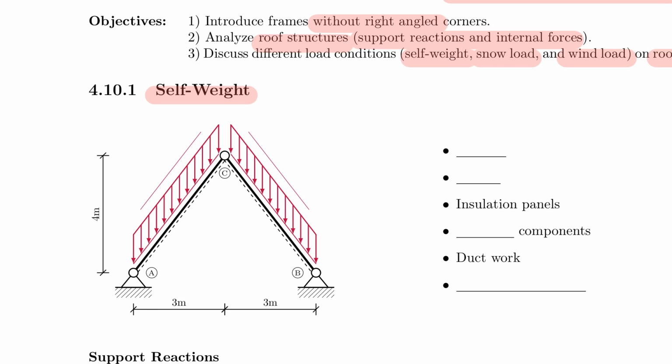So let's begin to write down some notes here. First of all, this is self-weight. In this particular case, for educational reasons, we'll just make it 500 Newton per meter. But please note that this is 500 newtons per meter along this beam and not along this horizontal direction, which could be misleading if you just look at these arrows.